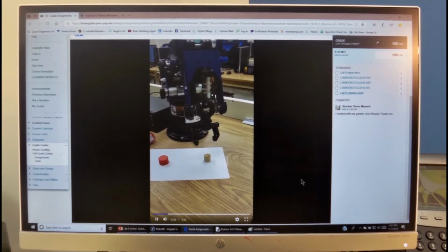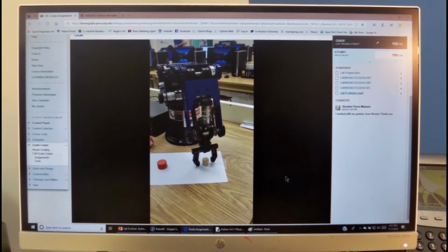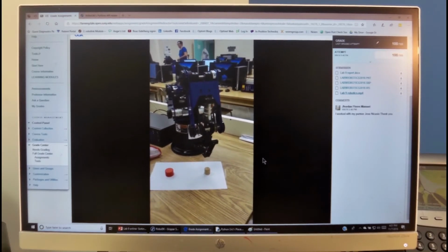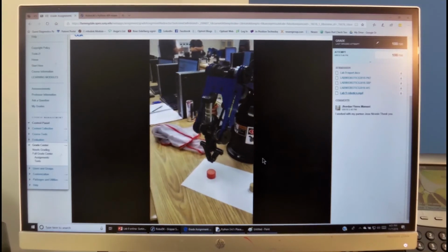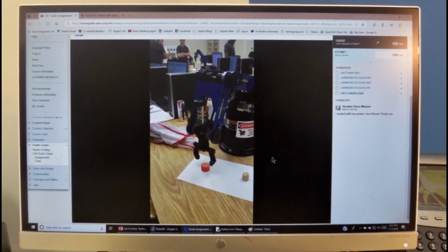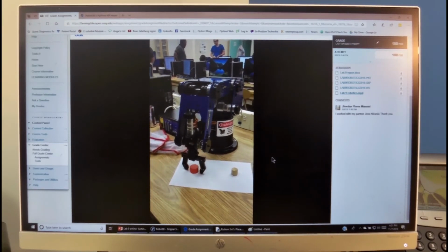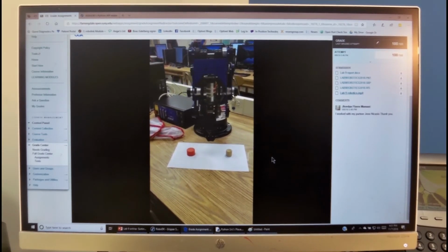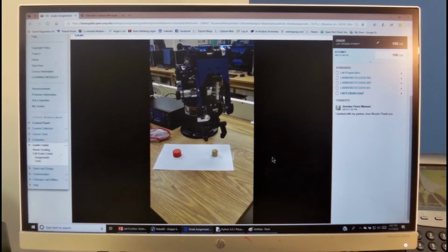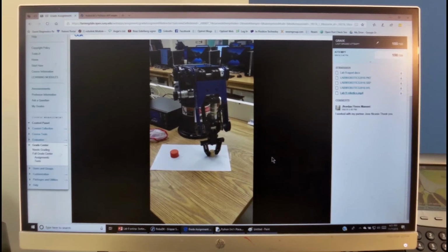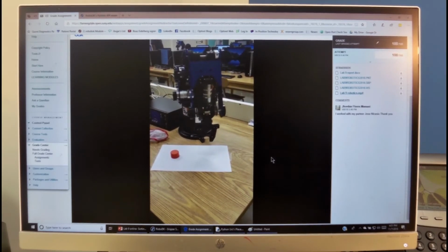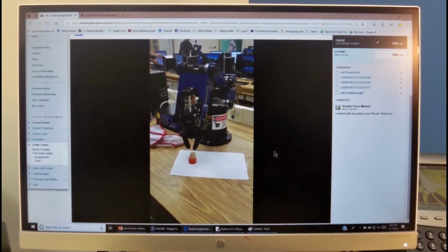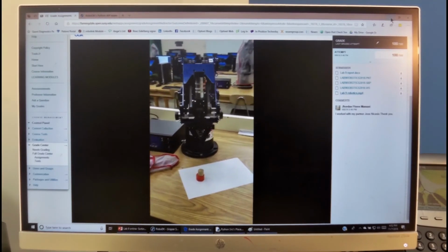The robot is coming in to the first station, measuring the diameter with the sensor built into the gripper, then going to the second one, measuring its diameter, then within the software comparing the two numbers, and then coming back to pick the smaller one, and then placing it on top of the large one. So that's the in-class operation.